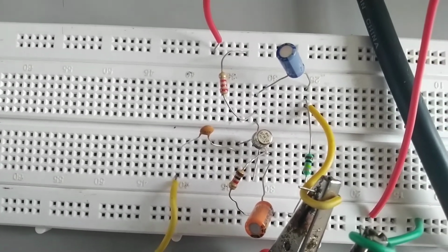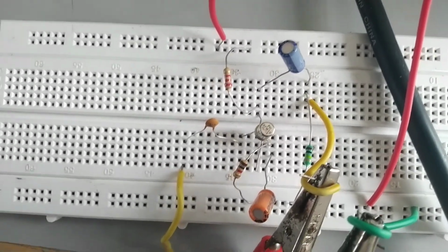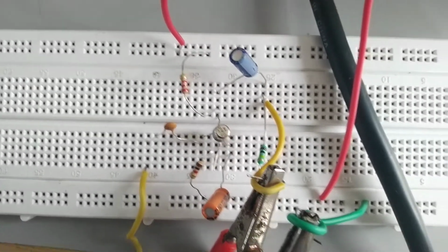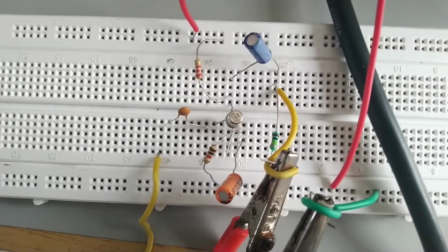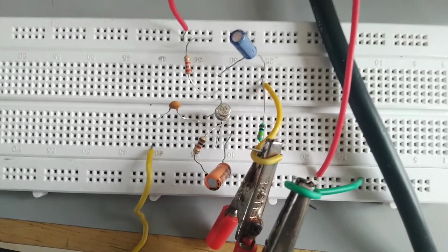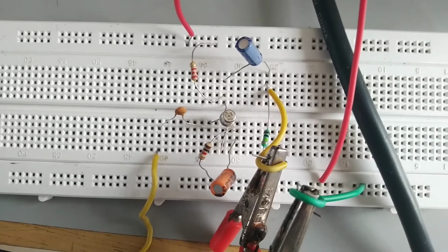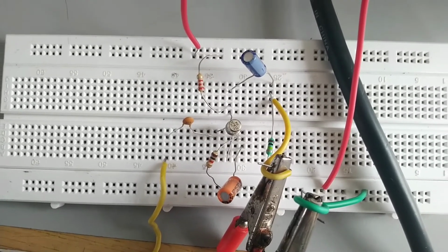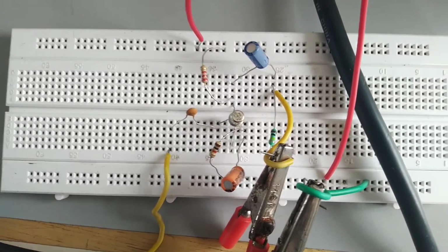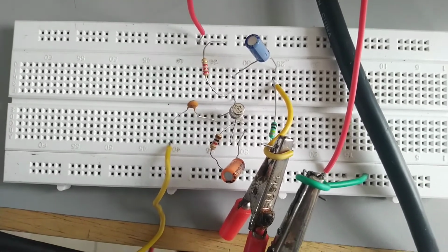From the diagram we know that we have 3 terminals: gate, drain and source. We are providing the input across the gate. From the schematic diagram we can see that the 0.1 microfarad is applied to the gate terminal, and then the 2.2K and the 1 microfarad are connected across the drain terminal, and for the source terminal the 1K and 10 microfarad are connected.